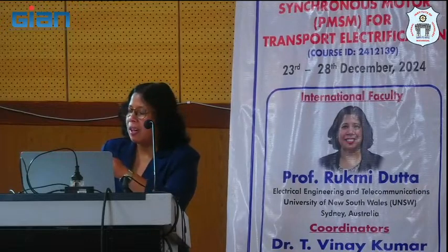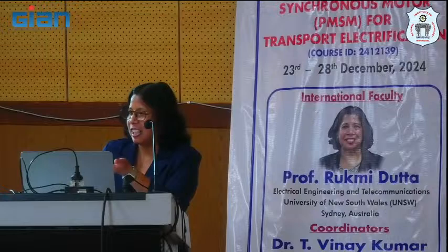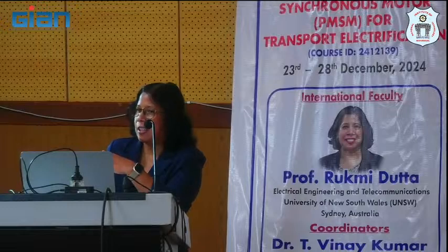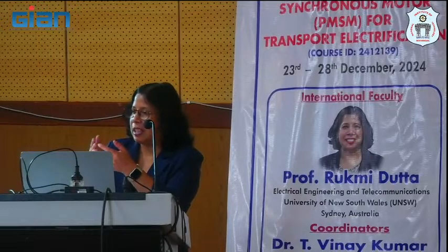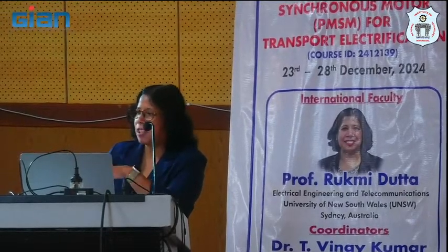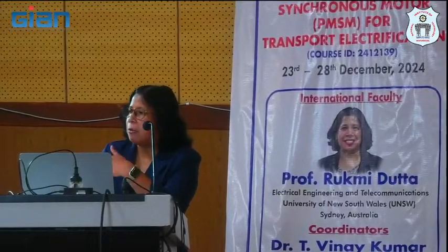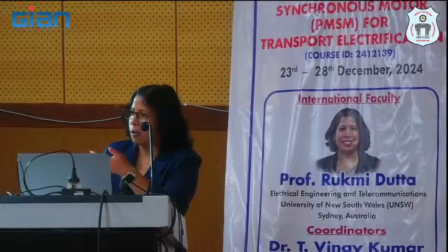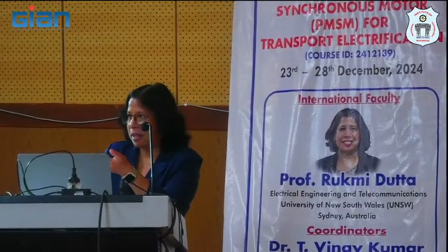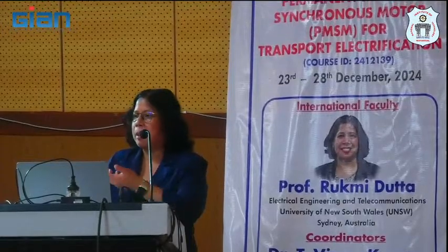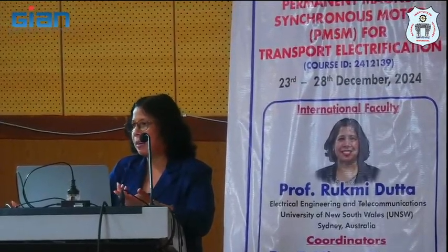So you have no option to start the machine from zero speed, right? If you're not injecting high frequency, there's no option. And sometimes even high frequency injection may not be allowed because injection of high frequency can cause again extra loss and extra vibration. So some application you don't have that option. So in that case, how do I start? But I still have a sensorless control. I don't have an encoder. For my high-speed test bed, I don't have an encoder because the encoder cannot work at that high speed.